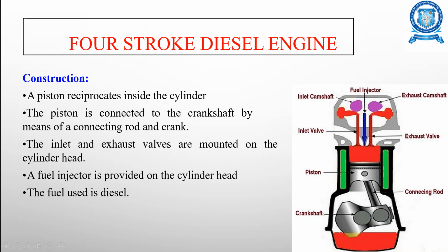You can see here you have a fuel injector, this inlet valve, and this is the exhaust valve, and this is the inlet camshaft and exhaust camshaft, which operate the inlet and exhaust valves. The inlet and exhaust valves are mounted on this cylinder head, and the fuel injector is also provided on the cylinder head.